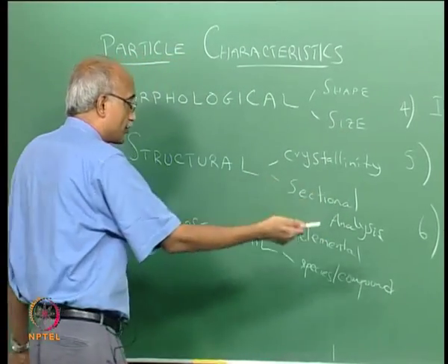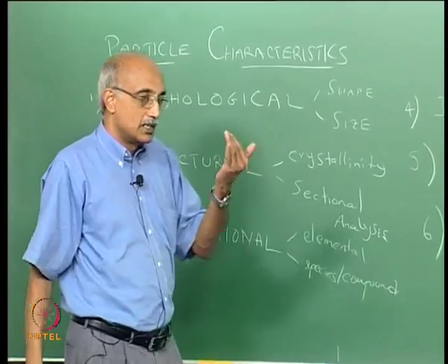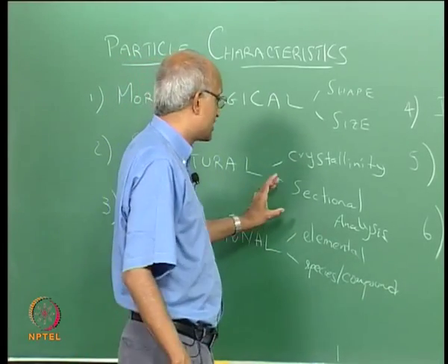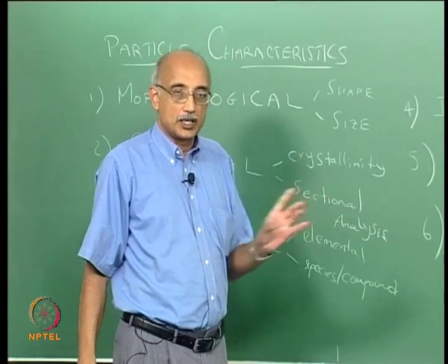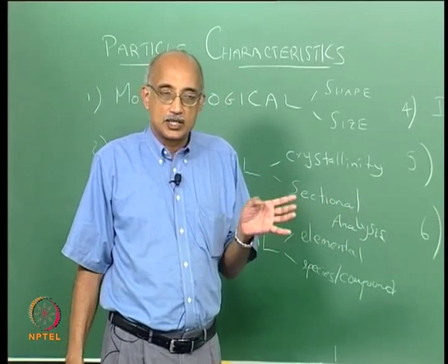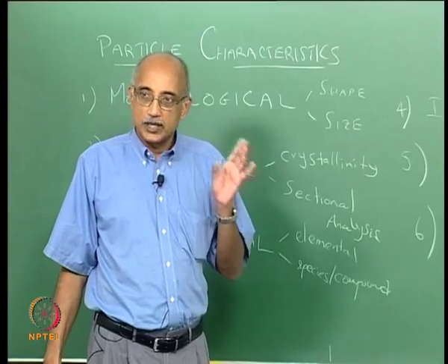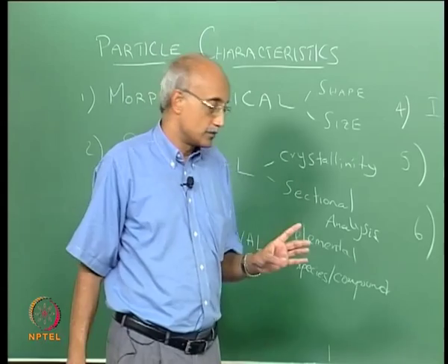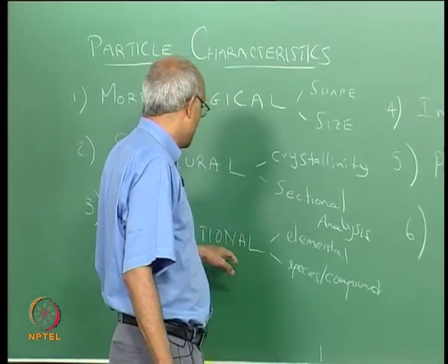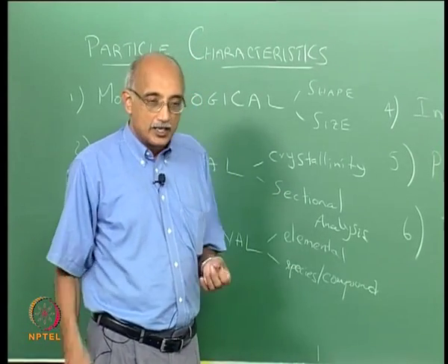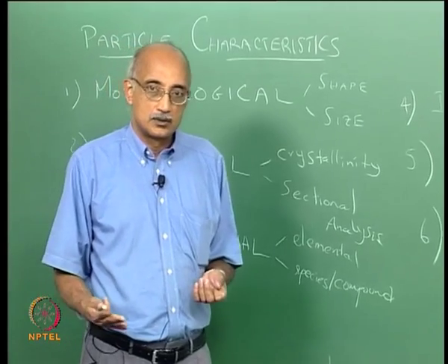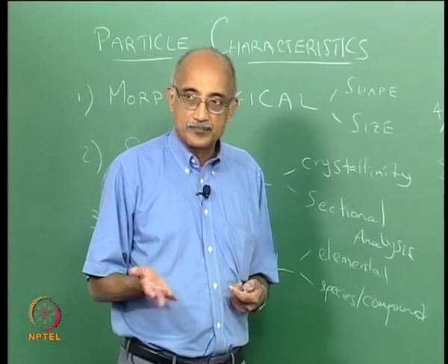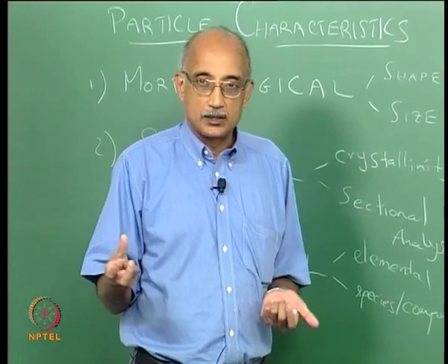So when we talk about crystallinity, or when we talk about sectioning a particle and doing a depth profiling of its structure, is that truly of relevance to your application, or is it something that's strictly of academic interest? You always have to make that call in your mind as to how much characterization is enough for the problem at hand. When you do compositional analysis, elemental analysis is the easiest. You can always use something like an energy dispersive X-ray analysis technique to get the element breakdown.